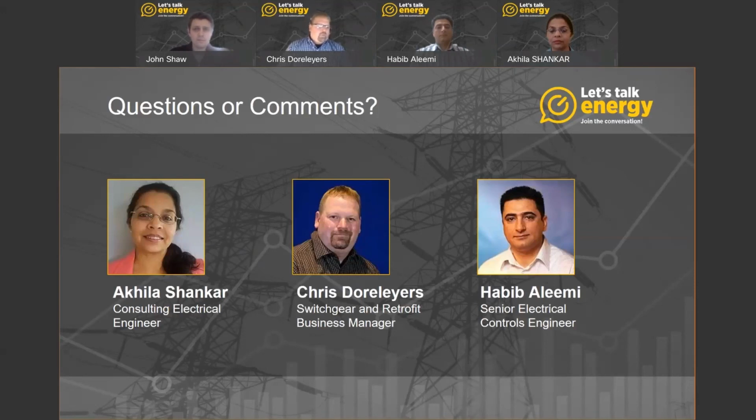With respect to controls, Caterpillar does offer controls that work with energy storage systems. If you're integrating with a microgrid as well, we can take microgrid signals and modify our control system to properly bias the base load set point of the generator with the microgrid.